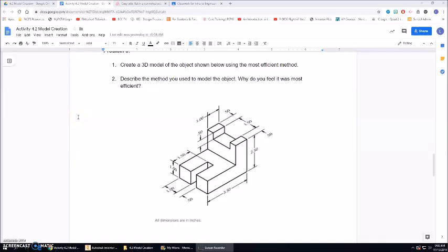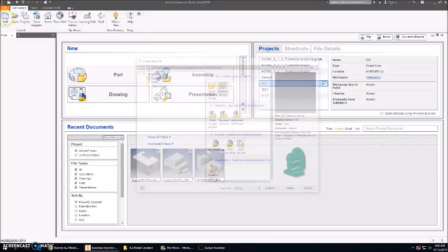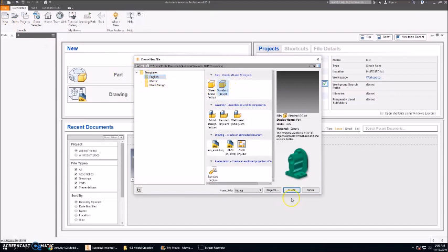Okay guys, we are going to take a look at problem number 3, and I'm going to do a couple of things differently here. One, I'm going to use a combinational method because I've used subtractive in the last 2. I'm going to choose a different plane, and I'm going to sneak in a new tool for you to check out. So we're going to bump over to Inventor, and we're going to hit New, English, Standard Inch IPT, and hit Create.